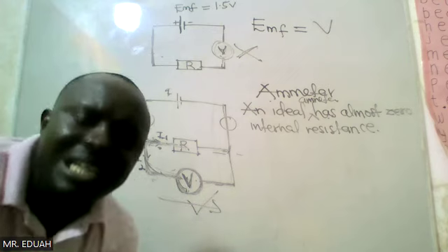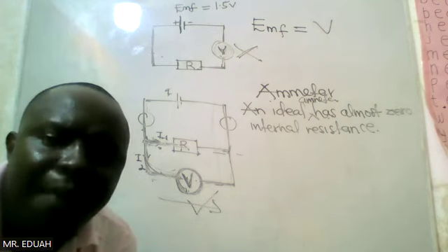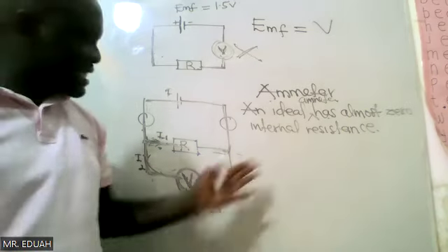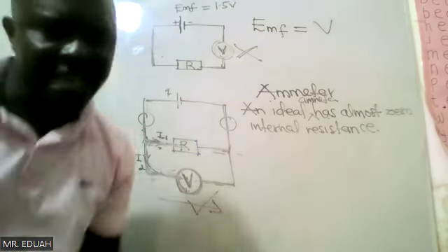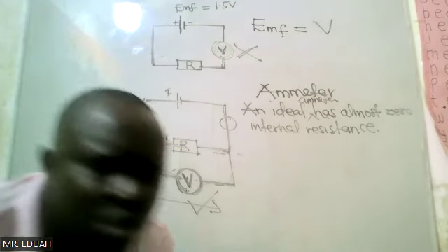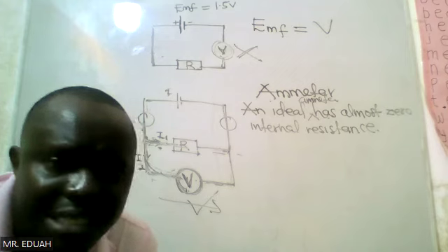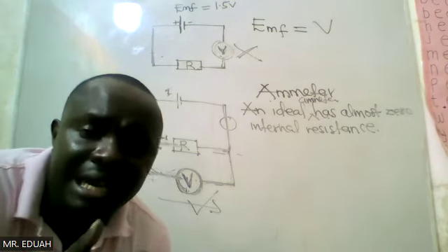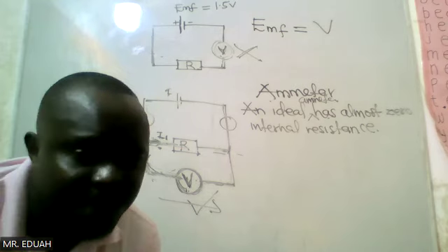And by designing it as such, you can measure maximum current. Imagine if it is designed to have a very high internal resistance. It would oppose a lot of current and then measure small. And when it is designed in that manner, it has defeated its purpose.